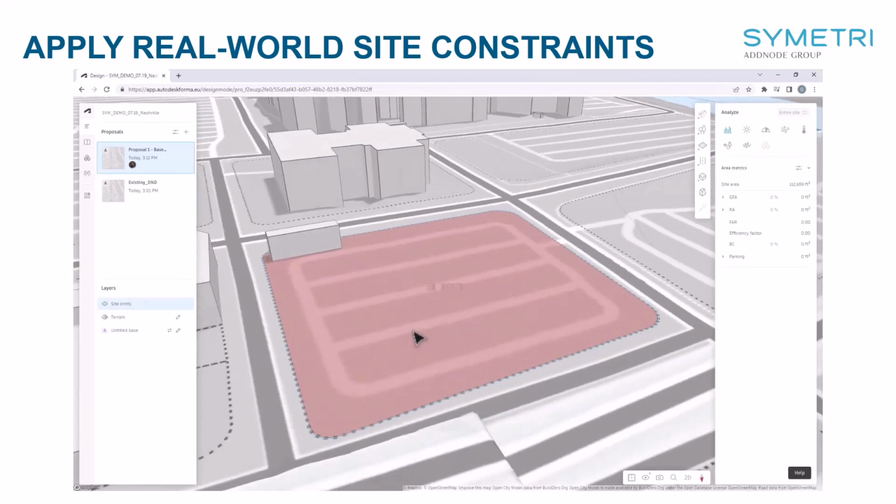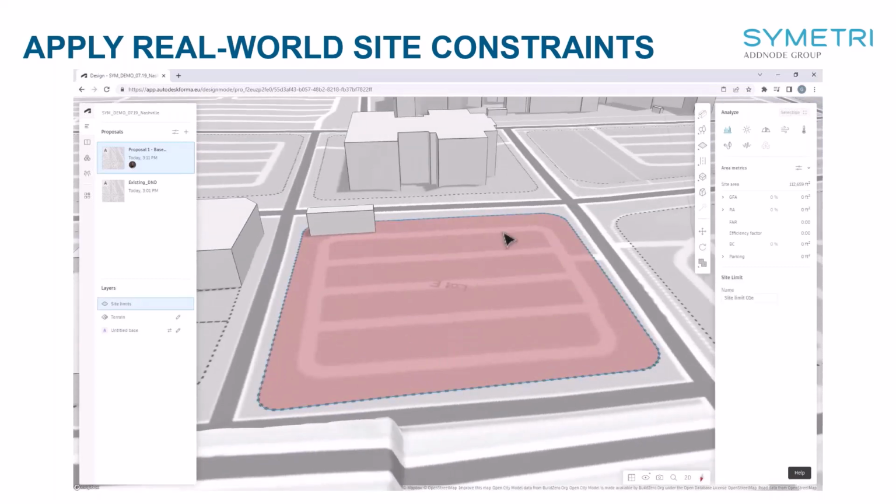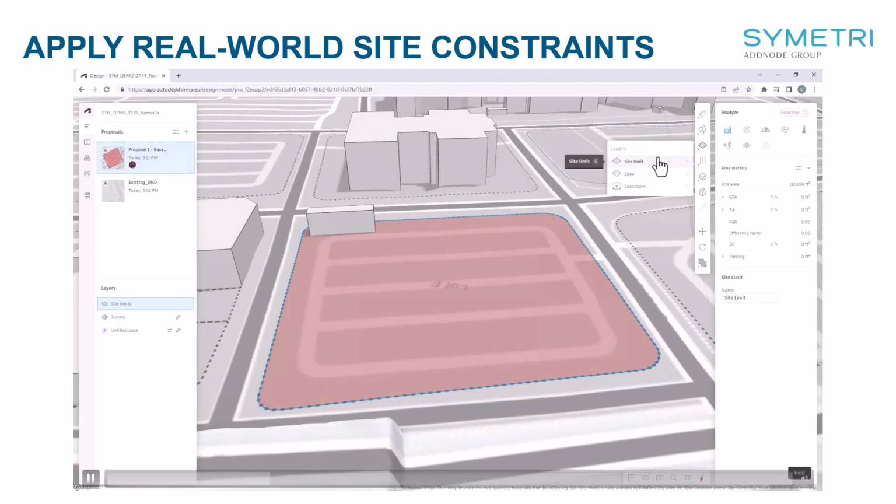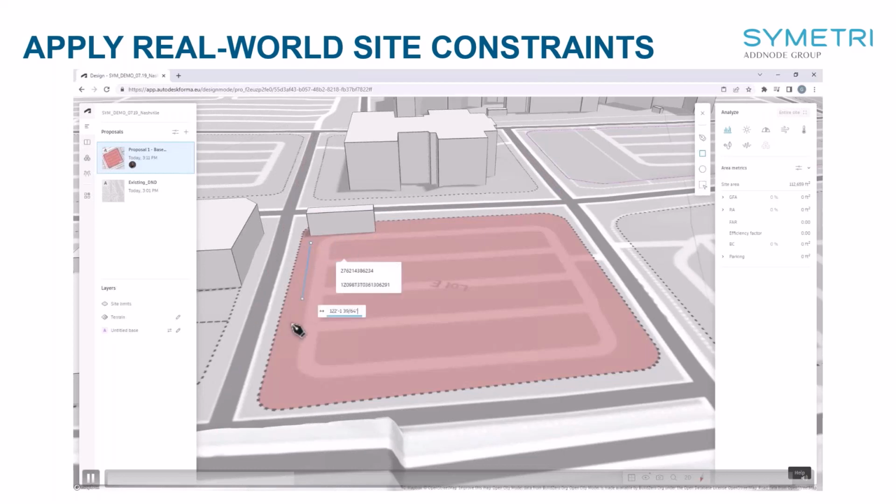And so the next thing we will do is look at the zones. Zones will allow us to segment the site in a way that creates an analysis where we can pick and choose from these different areas and program. So early in design, we might create a zone that is purely buildable space, right? I'm just going to use the rectangle tool, and we'll create that buildable space. That's where one of our buildings will go. Maybe this is the residential zone or something.